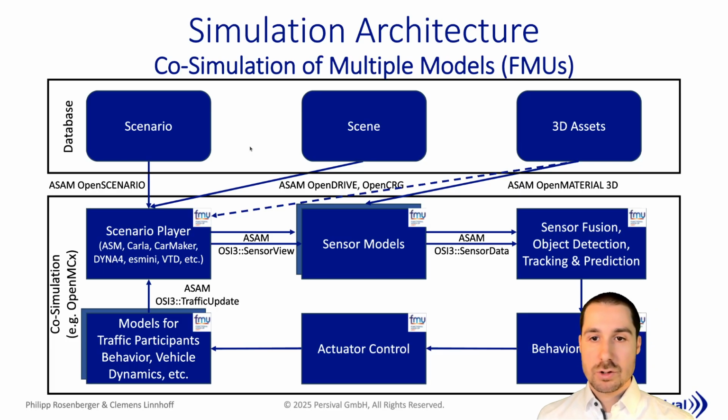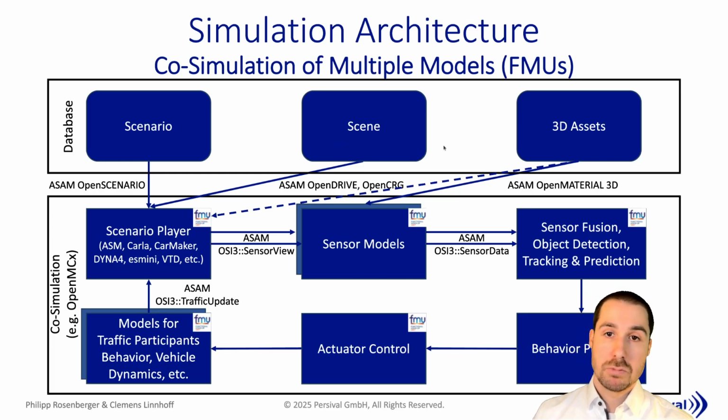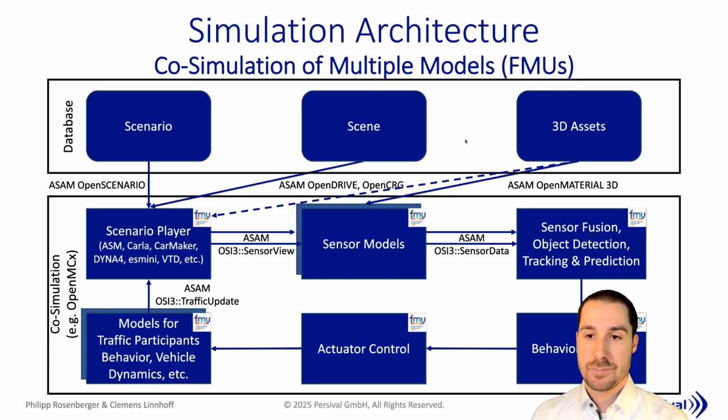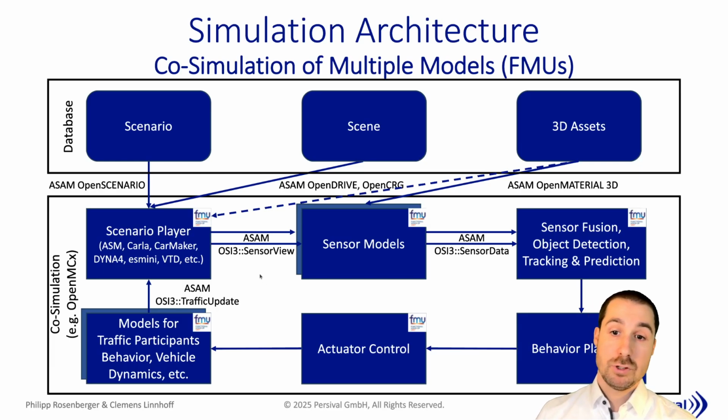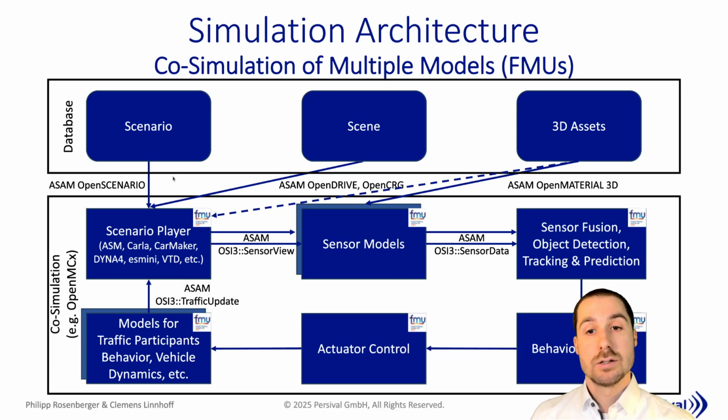Of course, first you need to define what is to be simulated. So you have some form of a scenario, you have a scene, maybe a map to drive on, and if you need rendering or more advanced sensor models, you also need 3D assets or 3D environment to simulate it. And then you have your models. First one typically is a scenario player. So you read in your scenario and the scenario player plays it back during the simulation runtime.